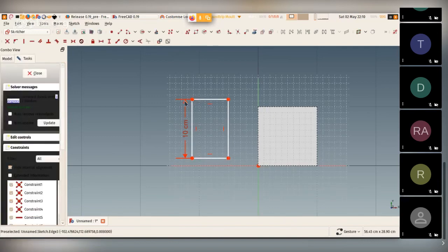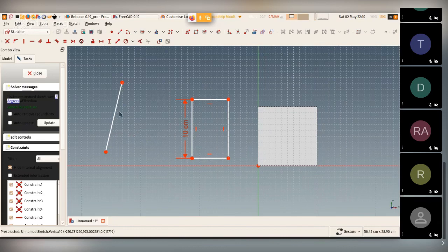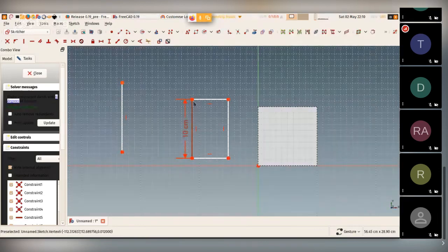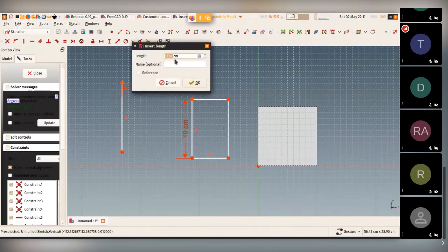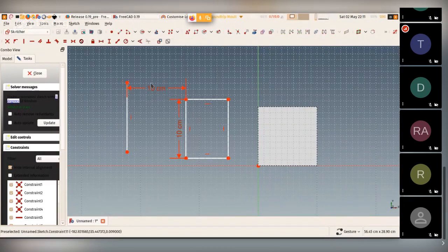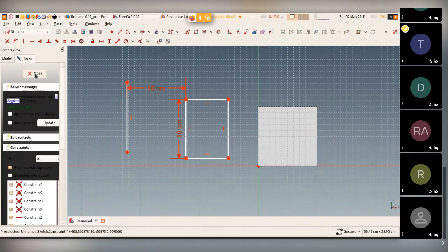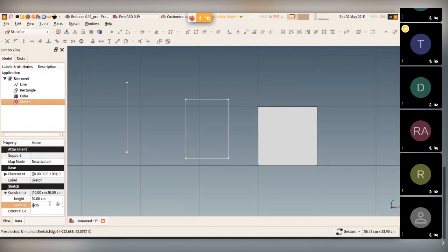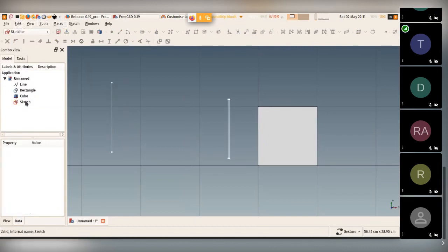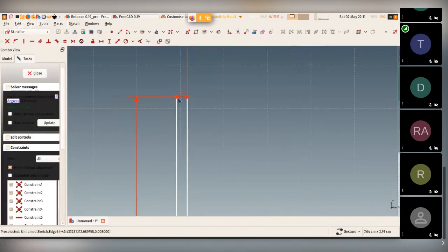Basically, you design this all the way you want. For example, let's say something else here. You see that I didn't do it vertically, but you can change this and add a verticality constraint, and then do things like this and put a horizontal distance here of 10, and then I can give this a name. And then I have spacing here that I can change. But of course, it calculates, I should have locked this as well, so it doesn't change.